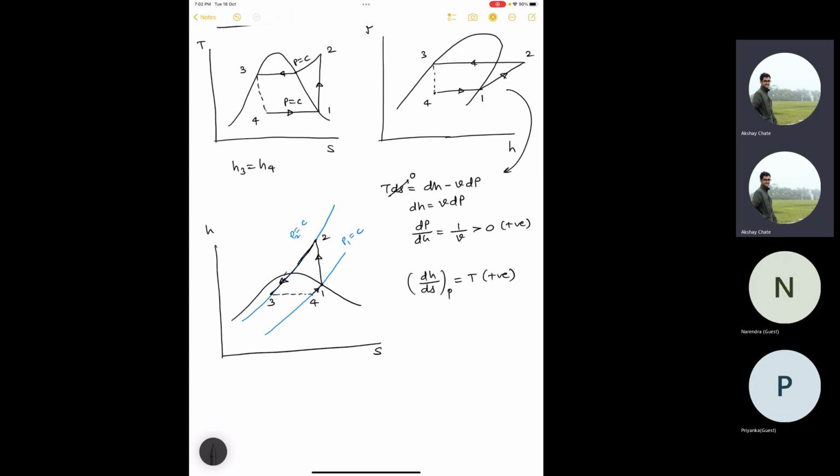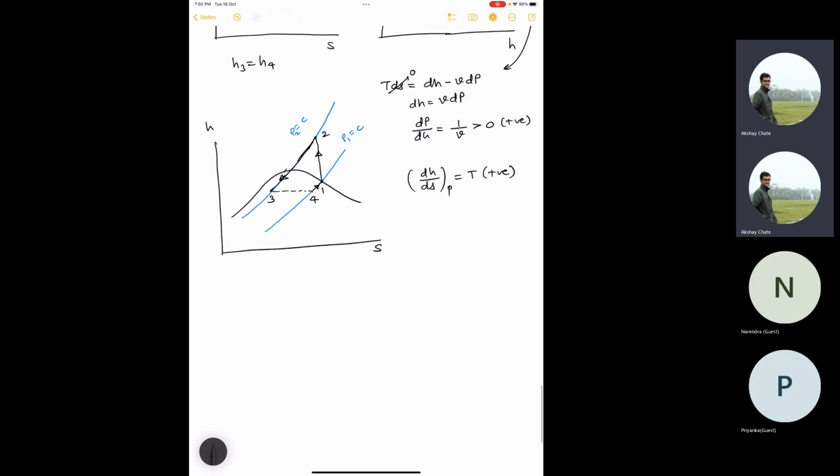Let me just quickly go through. Yeah, there is one more concept. If you remember, initially when we were studying reversible heat engines, we took 2 heat engines in series between the same heat source and heat sink, and we calculated the overall efficiency in terms of the efficiency of the first engine and the efficiency of the second engine. In case of refrigeration, you can do the same. You can have cascade refrigeration systems.